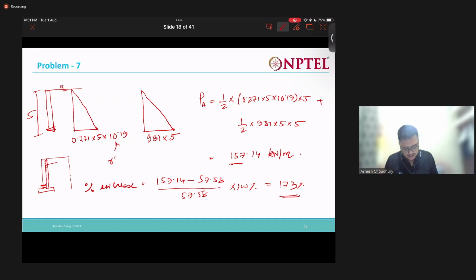So this geotextile material which we will be placing here will allow the water to flow from the soil material to the geotextile, but it won't allow the loss of the soil grains. It will just allow the water to pass through it. The water will percolate through it and get drained out through the weep hole, right? So it will be acting as a drainage material.